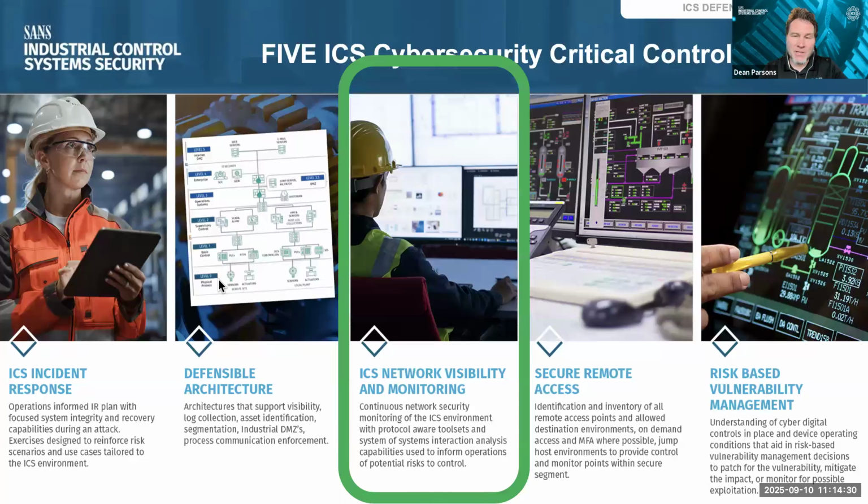packet captures, threat management, and threat understanding, threat detection, of understanding lateral movement, extracting network information for forensics analysis, extracting files that are laterally moved as well, understanding what is normal in the network and what is abnormal from an engineering perspective. That means visibility must have ICS capable or aware dissectors. It must understand those protocols we know and love that run our world, that makes and moves and powers our world. Modbus TCP, EtherNet/IP, and SIP, S7, for example, and so many others.